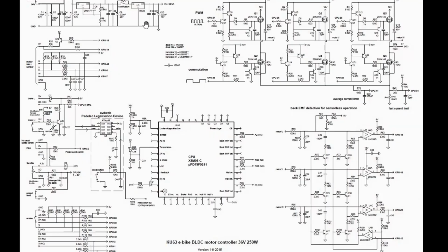On the left-hand side, top corner, there is a power supply, 5 volt DC, with some regulators and some capacitors. This is the ground symbol. Then there is one more part, the Hall sensor. The Hall sensor is for speed sensing and it can control. There is a microcontroller on the top, below where the arrows are going out. The supply is coming here. Inputs are there, like arrows, and this is the symbol for the ground and the supply voltage for controlling this.